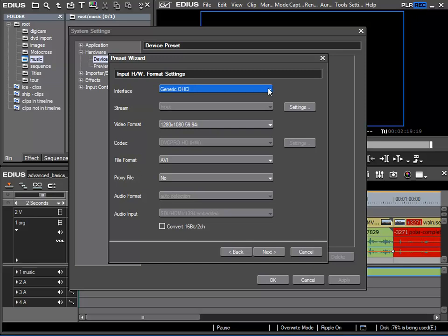And if I had, for example, a USB microphone attached to my computer, that could be via the Direct Show option, as a USB microphone would have its own driver, and so I could select it directly. In our case, however, I have a simple microphone attached to a preamplifier going into the line input of my computer, and so I have to choose the input Realtek High Definition Audio. This isn't a professional input, but I'm choosing it because I know that my microphone is attached to this.